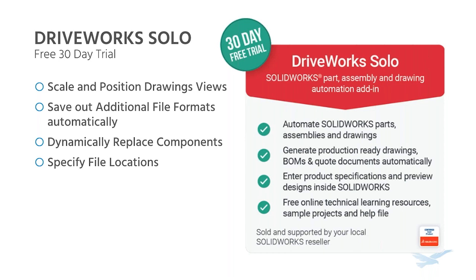The next step up from DriveWorks Express is DriveWorks Solo. The first thing to note is there's a free 30-day trial. You can just go on our website, download it, and start having a go. Some of the benefits DriveWorks Solo offers you when compared to DriveWorks Express, and this is one of the questions that's been asked by Christian, I think, is that we can control the scale and position of drawings. This lets you create production-ready drawings. Inside DriveWorks Express, although we can generate a brand new drawing, we can't control that scale and we can't control that position. So what that means is you might have to perform some manual adjustments to the drawings that you're producing with DriveWorks Express.